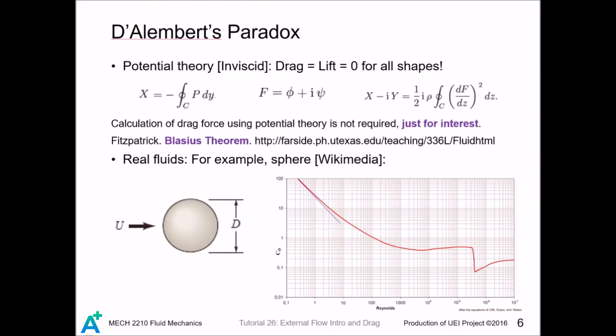If you recall that the uniform flow involving incompressible fluid is indeed potential flow. For potential flow, and if we further assume that the flow is inviscid, then we can apply the Bernoulli equation. Since the shear contribution has gone away, the drag force is simply contributed by the pressure force, and it can be written this way. And people develop this expression for finding the drag and the lift force under potential flow.